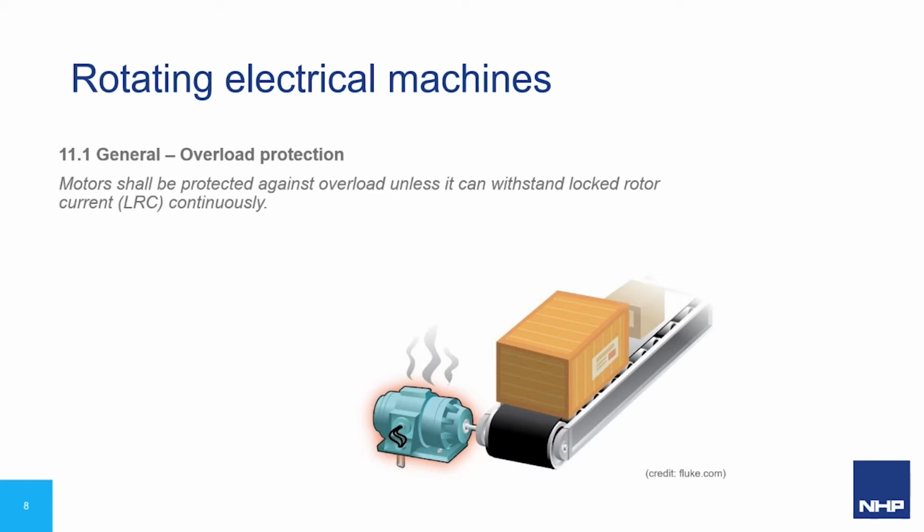And it would mean that the motor would need to be rated to withstand stall and fault conditions like the ones shown here, where the load is simply too large on the conveyor and it has stopped. And the ability to withstand the locked rotor current would come into the design of the motor, and this would increase the thermal mass of the motor to assist in dissipating heat to prevent the high surface temperatures occurring. But this would also increase the cost and size of these EX rated motors more than what they already are, which is why you don't often see these.